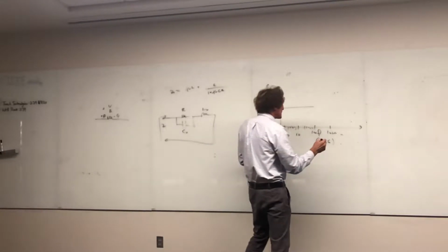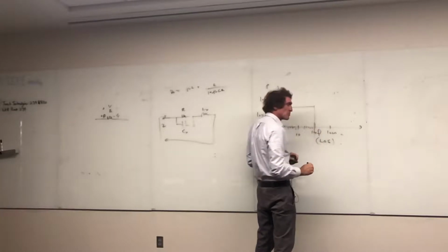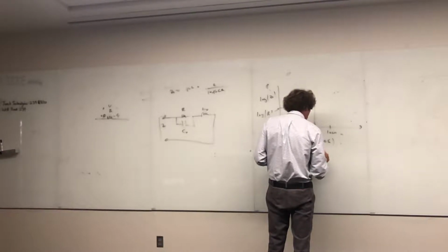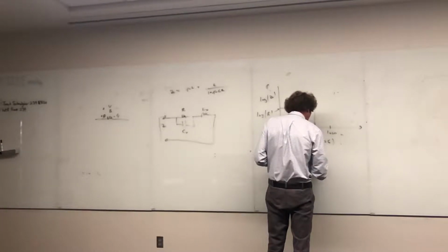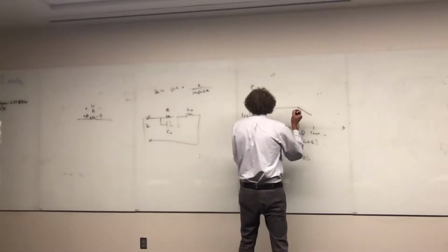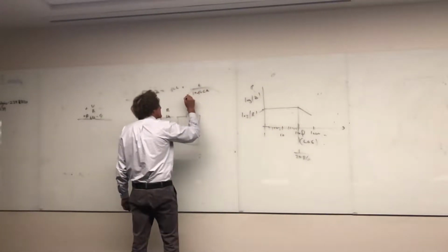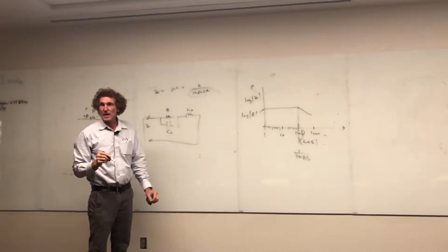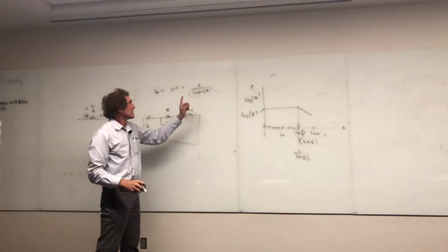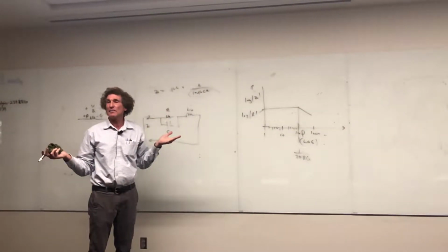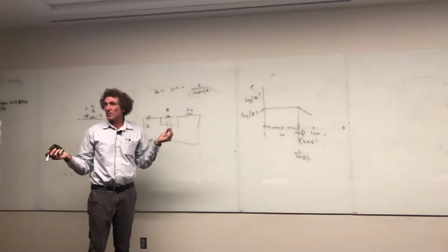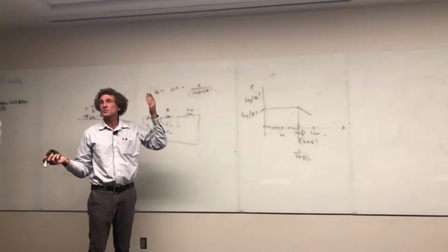And it stays there until it hits its first cut frequency. I call it a cut frequency or break frequency. This frequency is going to be 1 over 2 pi times R times Cx. That's the first frequency, and it's going to start going down after that part, because that's when this all of a sudden becomes a factor. When j omega R times C equals 1, then I have 1 plus j1. That's the point when we come down. If you take the magnitude of 1 plus j1, it's the square root of 2. It's always going to be square root of 2 at the break frequencies on all these things, whenever you get a square root of 2, increase or decrease.